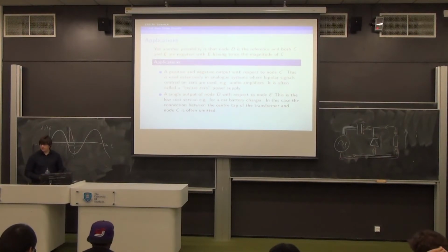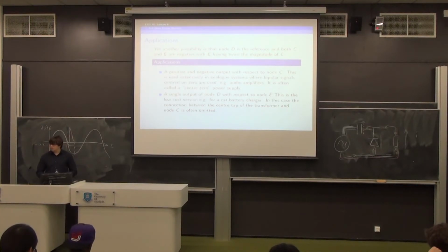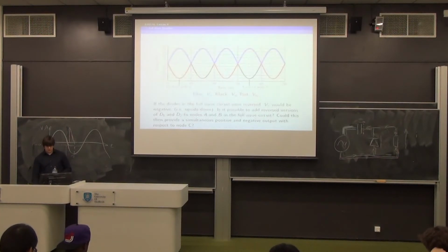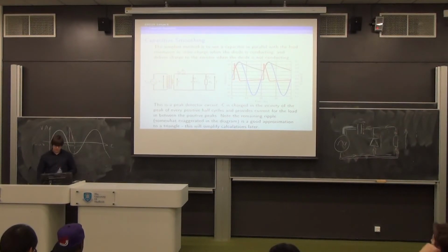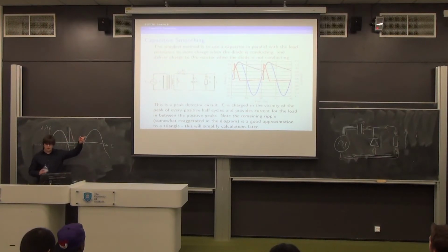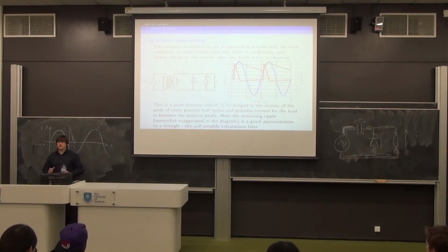And similarly, in the half-wave circuit, as long as you've got a transformer in there, you could, if you wanted, make the upper point of R1, where I've got the current flowing, 0, and you'd have minus a certain output voltage on the bottom of R1. It's entirely up to you, depends how you want to wire it up.